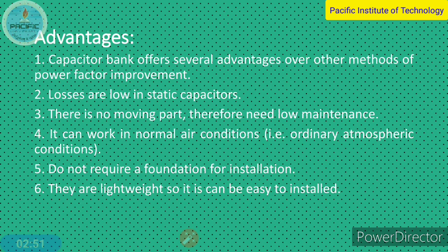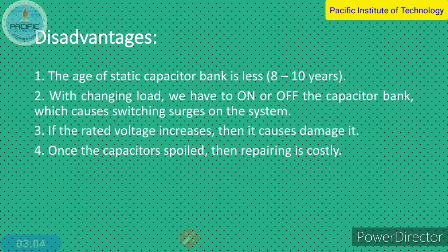The installation foundation is required in case of a synchronous condenser. They are lightweight, so they are easy to install and uninstall. But there are certain disadvantages also of using a static capacitor. The age of a static capacitor bank is less, about 8 to 10 years. So after 8 to 10 years, you have to replace the static capacitor bank.